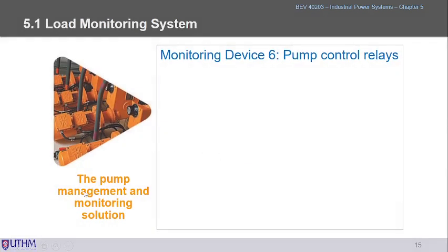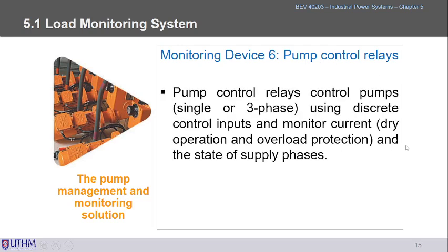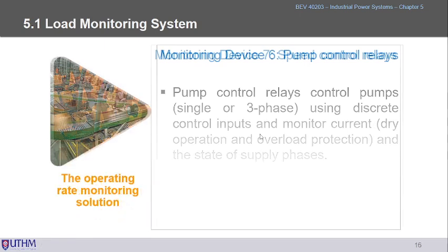And for pump management, of course we can use pump control relays. These can control either a single phase or three phase pump. We can monitor the digital control inputs and the currents, I mean the dry operation and the overload protection for the pump.